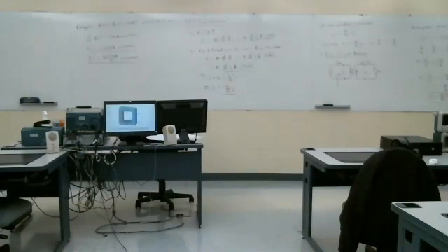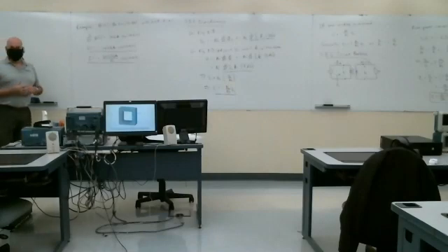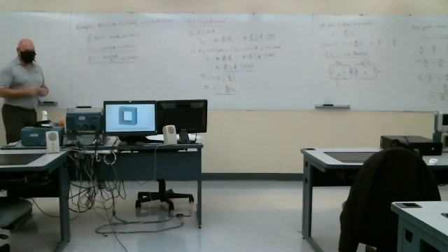Transformers can provide voltage gain, but if they're providing voltage gain, the current is less. The output power for a transformer at best is the same as the input power. For practical transformers, the output power is actually always less than the input power because there is some loss in the transformer itself. But transistors actually provide power gain, an increase in both voltage and current.